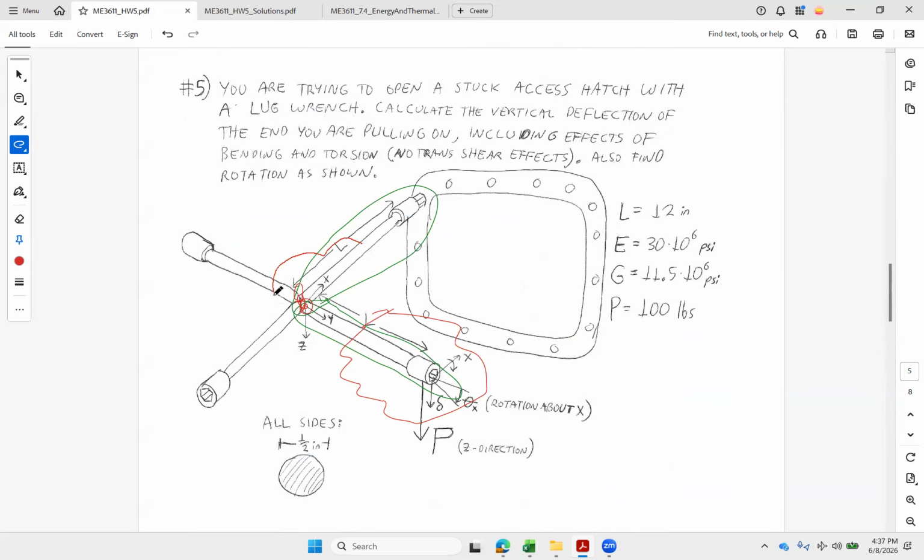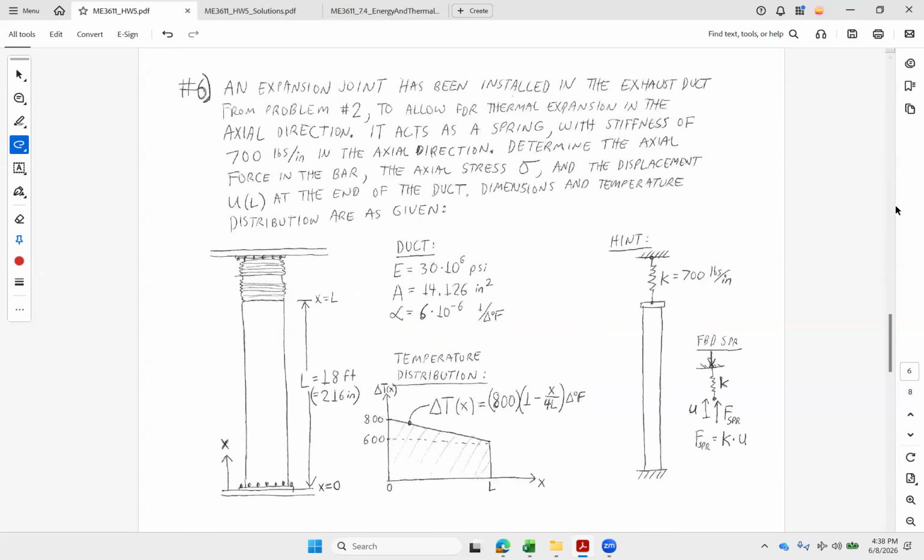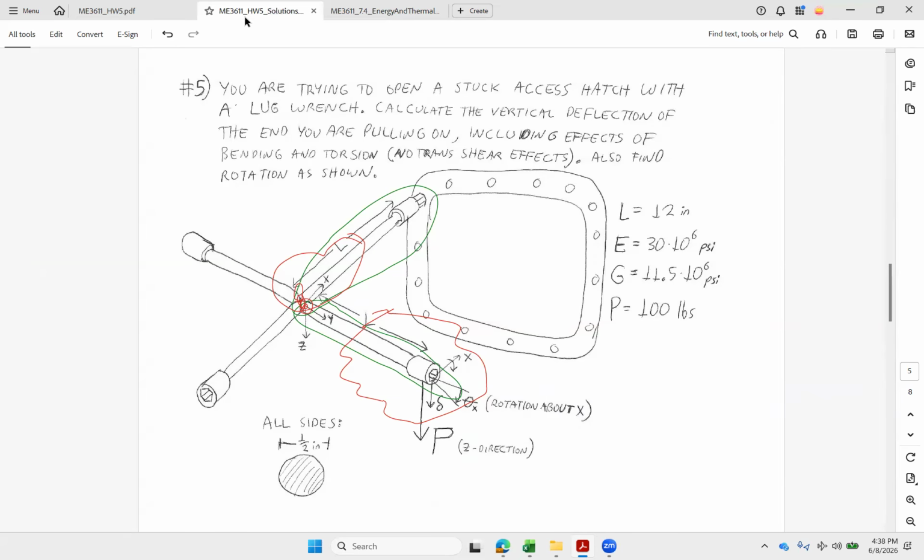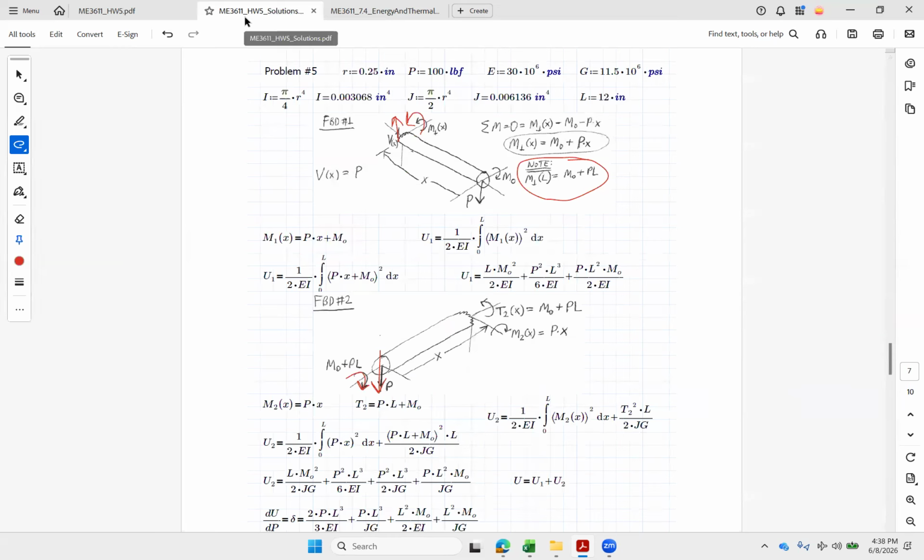So I could take a little slice and keep right here, or I could figure out the reactions and keep the root end of the beam. Either one is fine. Whichever one you're more comfortable with is what you ought to do. I transferred the load since we already did the work to get V and M on the first one, we can just flip them and put them on. And I see the axis that was bending on beam number 1 is actually a torsional axis because we made a right turn on beam number 2.